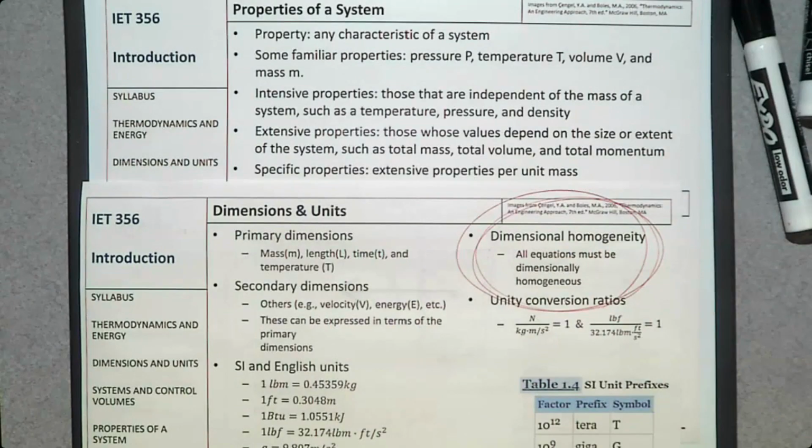And then how can you make temperature into an extensive property? Multiply by mass. What is the physical meaning of temperature times mass? There is no physical meaning. So converting all the properties in an equation into extensive properties doesn't make sense. So we prefer using only intensive properties. Then what about the mass? What about volume? What about momentum and energy?